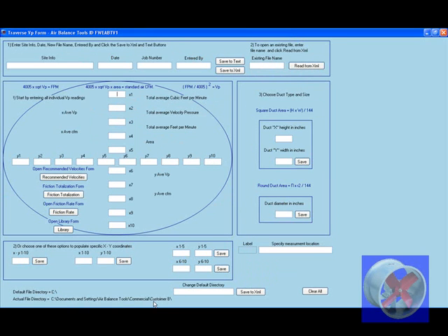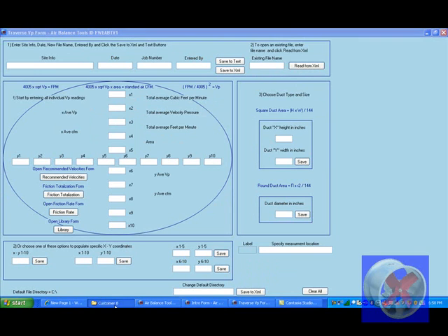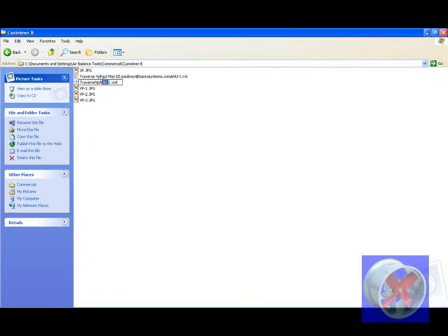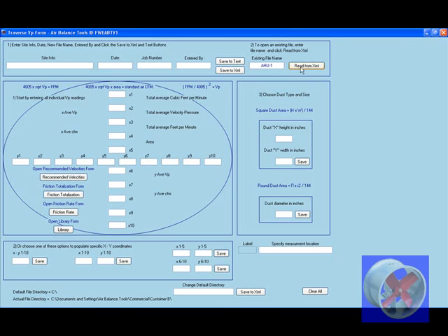So we have our file directory set. Now we're going to go ahead and identify what our file number is going to be. Air handling unit number 1. Okay, so this particular air handler is a 30 by 40 inch air handler. It produces about 12,926 cubic feet of air per minute at 0.15 inches of velocity pressure.